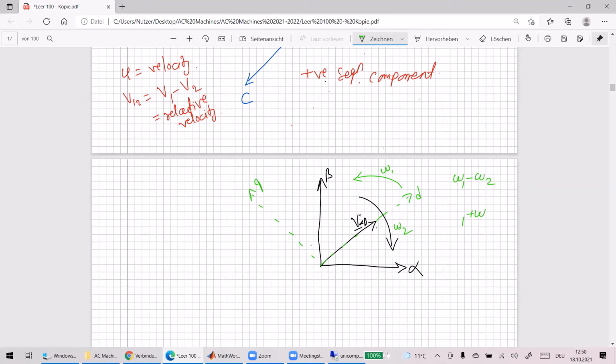But if you see here, their direction is different, right? So if I just want to see the magnitude, let's say this anti-clockwise is positive, and then this would be omega 2 magnitude and then minus. So it will be omega 1 magnitude plus omega 2 magnitude. So you would see omega 1 plus omega 2. So if both are 50 hertz, what frequency will you see? 100 hertz. So in the DQ frame, if a negative sequence component is there, you will also see a 100 hertz component.